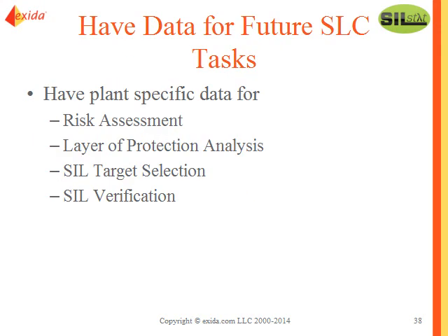You have data for future lifecycle tasks: risk assessment, layer of protection analysis, your SIL selection, as well as your SIL verification. That's what you get when you collect your data. You don't have to rely on your industry data books anymore, or you have verified that those industry data points actually apply to your particular plant.